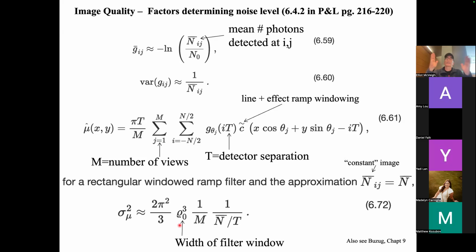So when we have this ramp function and we open up and we say, we want higher frequencies, I need to see smaller objects, I open it up, and the noise jacks up by the cube of that width. So those are the interesting relationships between how you would design a scanner and how you design your recon to get variance in the pixel values that you're comfortable with.